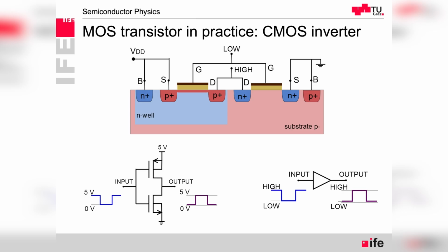This structure will be explored, and lots of peripherals can be added so that the frequency of the oscillation stays stable. Generally, what we always look at for the ring oscillator is the on resistance and the load capacitance. If we want to achieve a high frequency, we need a small number of stages, the minimum being 3.